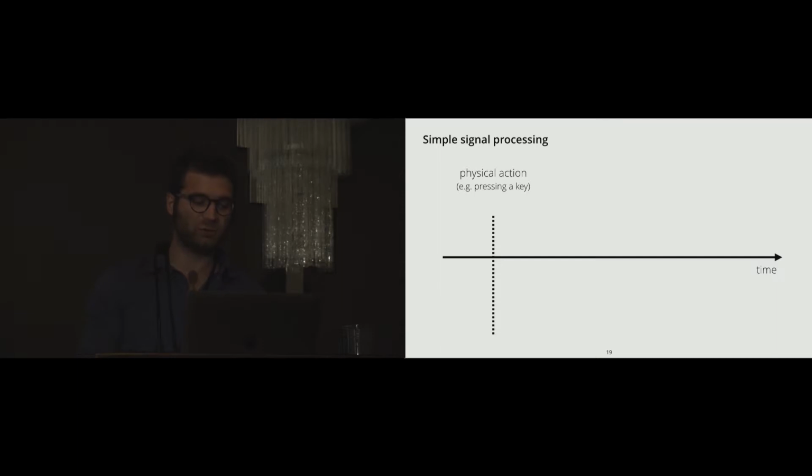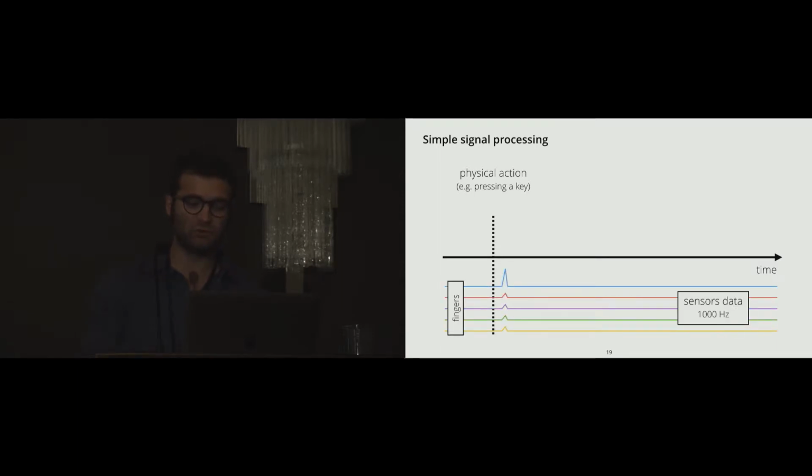The values of the vibration sensors are sampled at 1,000 Hertz, which is much higher than the frequency of low-level event detection, around 100 Hertz. The algorithm retrieves the max value within an empirically defined time window of 30 milliseconds, and this time window can be customized depending on the hardware used. The device is inherently real-time since finger identification is available as soon as a software event is detected.